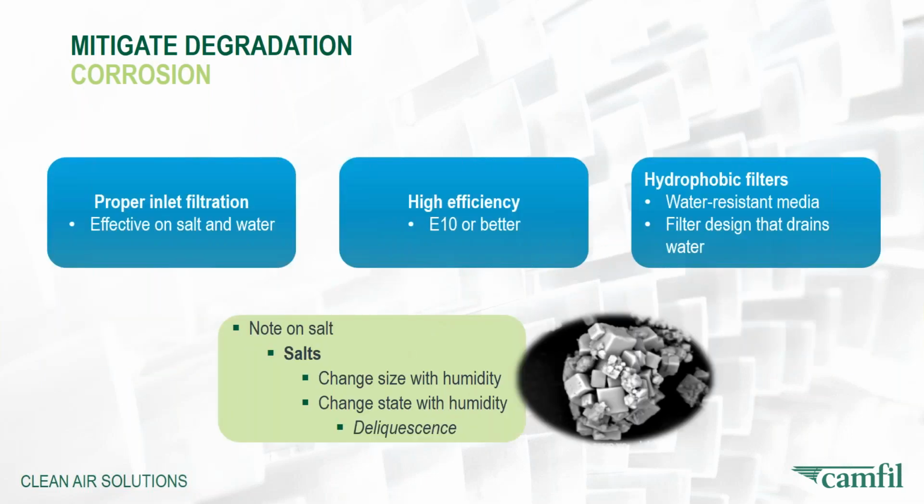By proper filtration, it needs to be effective on the salts, on those small salt particles and moisture coming in. With respect to the particulate, we mean a HEPA level efficiency or better: 85% on small particles, 0.2 micron or smaller. In some cases, you need to be even higher than that.